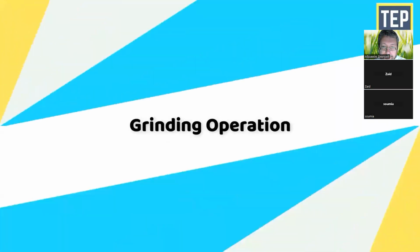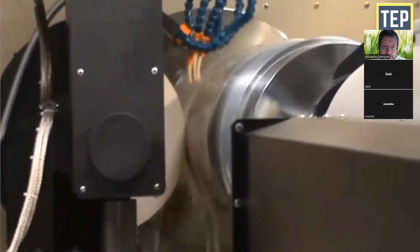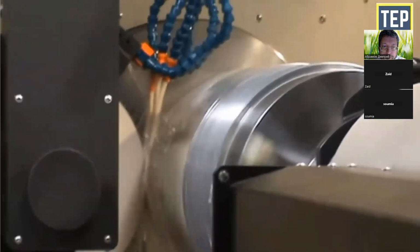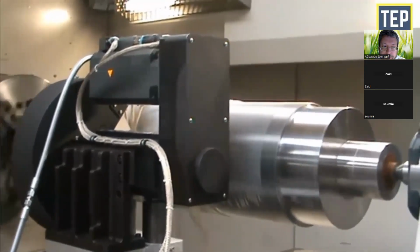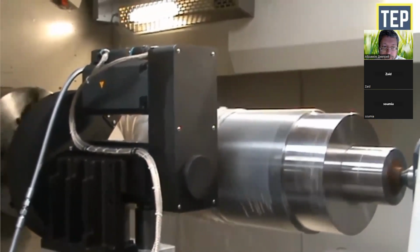Grinding operation. Grinding is the operation of removing the metal in the form of mini chips by feeding the work against a rotating abrasive wheel, known as the grinding wheel. Both internal and external surfaces of a workpiece may be ground by using a special attachment mounted on the cross slide. For grinding the external surface, the work may be revolved between centers or on a chuck. The feeding is done by the carriage, and the depth of cut is provided by the cross slide. Grinding is performed in a lathe for finishing a job, sharpening a cutter, or sizing a workpiece after it has been hardened.